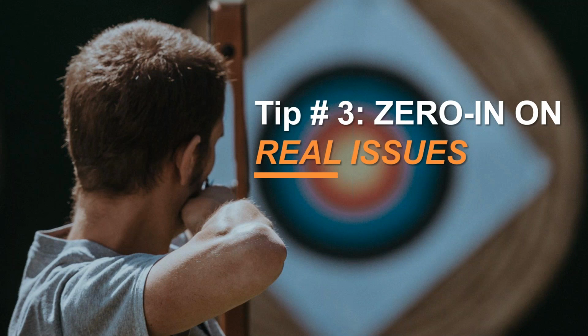And because of that, they identified an incorrect die design and placement, which caused the consistent stoppages, and the input was passed on to the die design and die setter team. So they realigned the way the product drops onto the conveyor belt and eliminated the short stops for that product. So by highlighting these things, you can zero in on the issues once you've identified them.